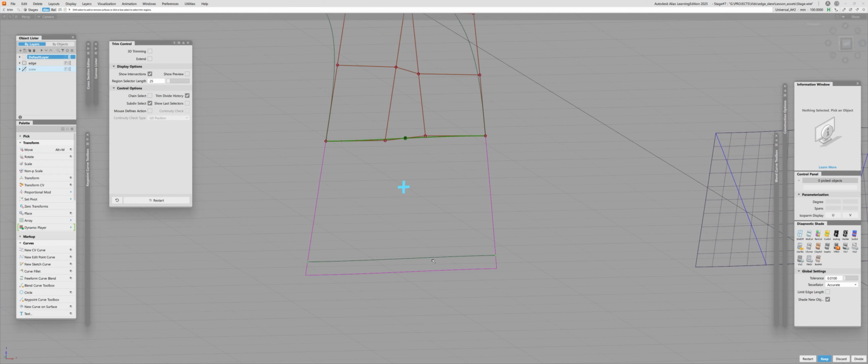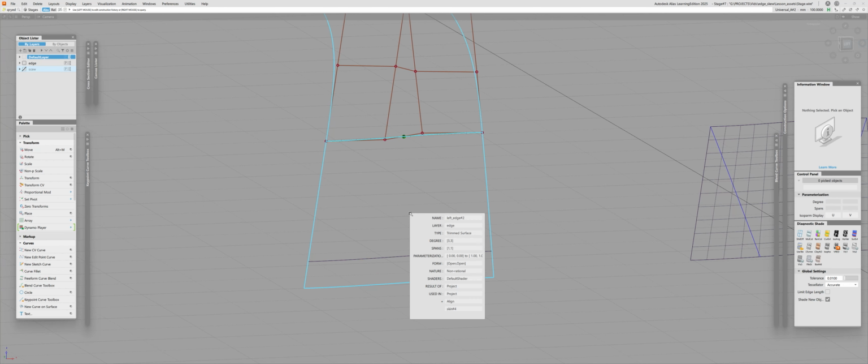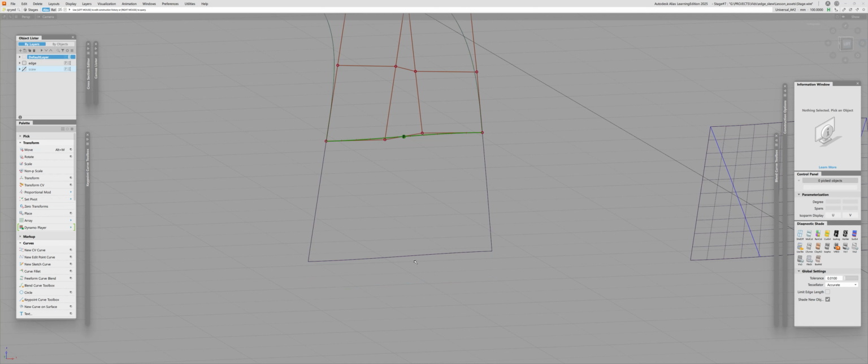Now, if I trim the surface like this, and check it again, you're going to see nothing changes. So the reparameterization didn't happen. The parameters are still within 0 to 1 because we didn't change the surface. We just visually trimmed part of it, creating an additional arbitrary edge.